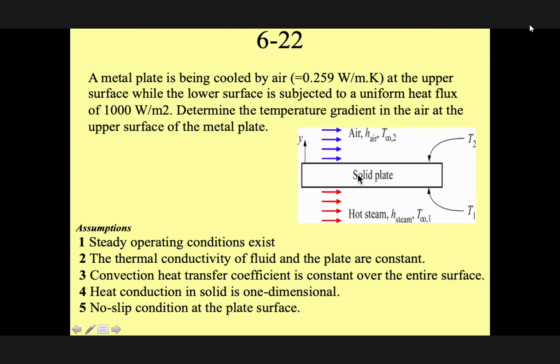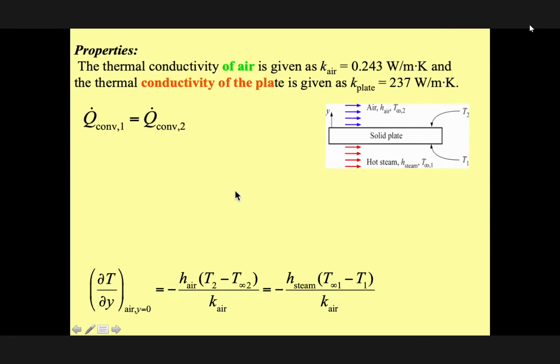Therefore, what we did, we have to try to find the temperature profile here. We know the temperature of the air after the boundary layer, at infinity, but I do not know the temperature here. What we did, let's look at here. The convection here is equal to convection here, which is equal to conduction through here, okay? I'm not interested in conduction to the solid. I'm interested in conduction in the boundary layer. Therefore, we wrote convective here, the value is known, it gave us 1000. This is the convective heat transfer from the surface to the bulk. This is the temperature of the bulk.